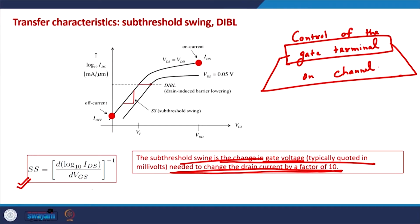Okay? So, we would always like to minimize the subthreshold swing parameter in MOSFETs, and there is a fundamental limit up to which this can be minimized. So, for a MOSFET, the subthreshold swing is always greater than or equal to 60 millivolt per decade. 60 millivolt means that at least a 60 millivolt change in the gate voltage is required in order to change the drain current by a factor of 10 in the subthreshold regime of the transistor.